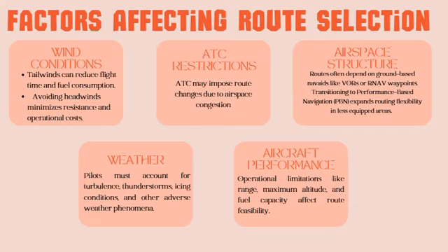Air traffic control restriction. To manage airspace capacity, ATC may impose delays or reroute traffic to prevent congestion. These adjustments often prioritize safety but can affect efficiency. Also, ATC assigns predefined airways for IFR flights, limiting flexibility in direct routing. Innovations like user preferred routes allow airlines to suggest optimized paths subject to ATC approval.